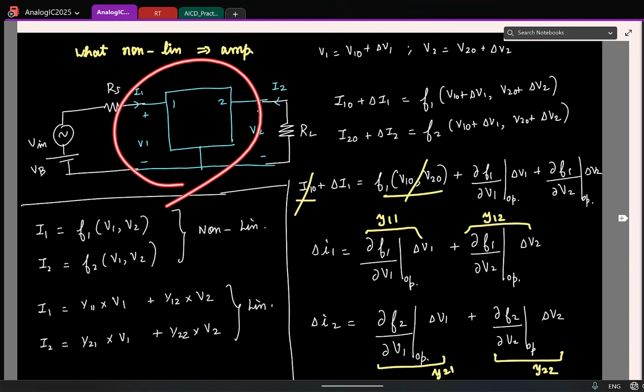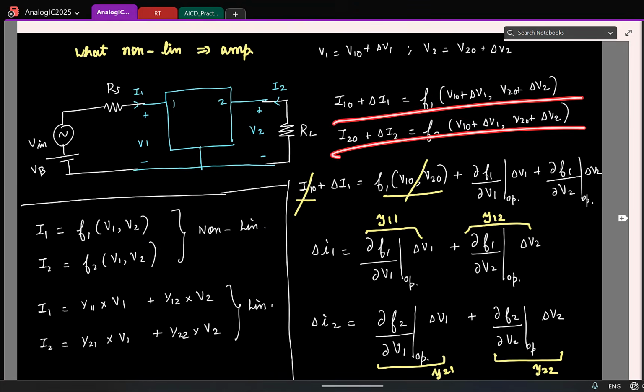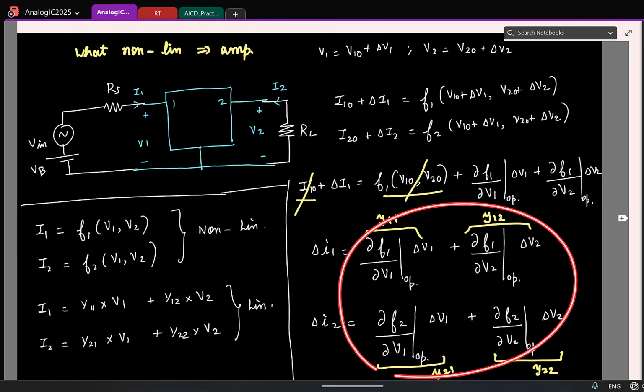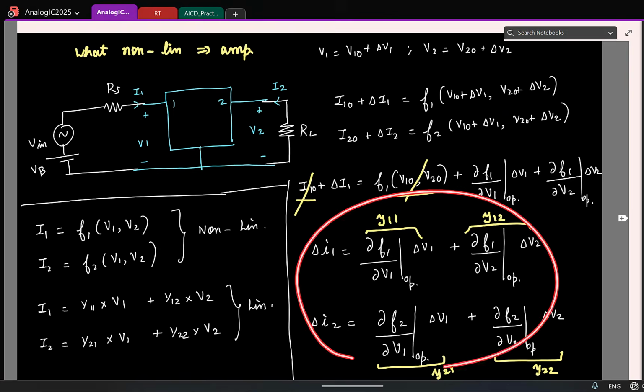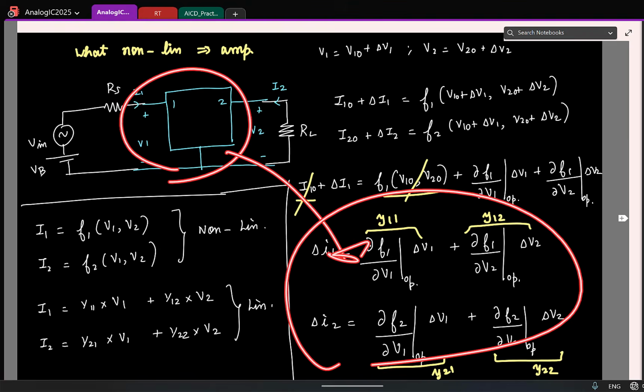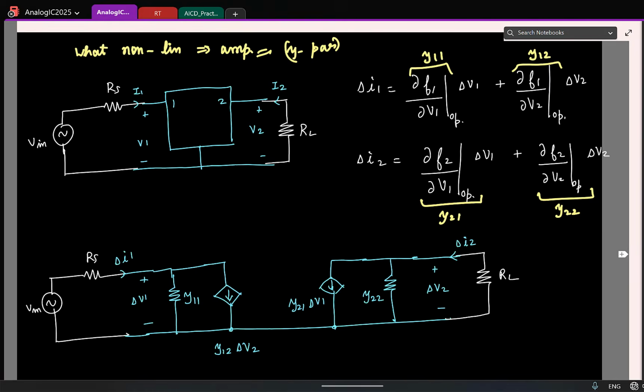So we moved to a 3-terminal 2-port nonlinear network. So again, this has a nonlinear relation, and we wanted to find out how this nonlinear relation should look so that we get power amplification. So once again, we took this nonlinear equation and expanded it using Taylor series. Assuming signals are sufficiently small, we ignored the higher order terms, so that gave us only this linear equation, which means for small signals I can model this nonlinear network according to this equation, and that turned out to be this.